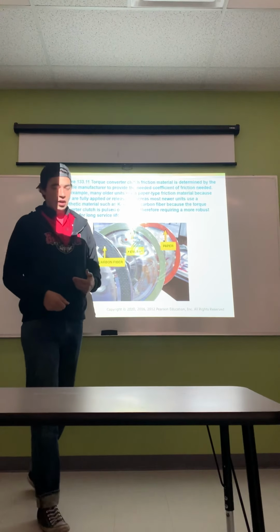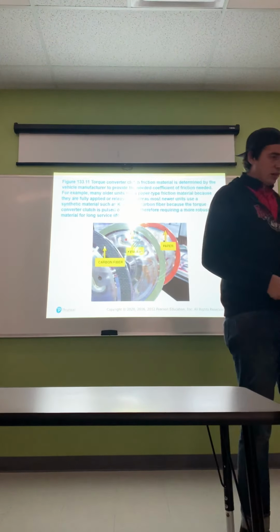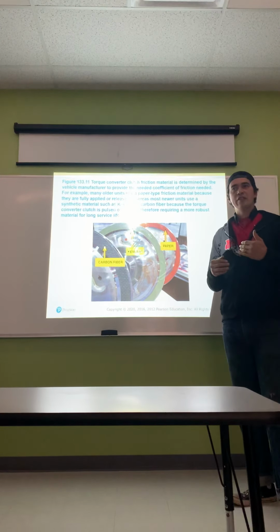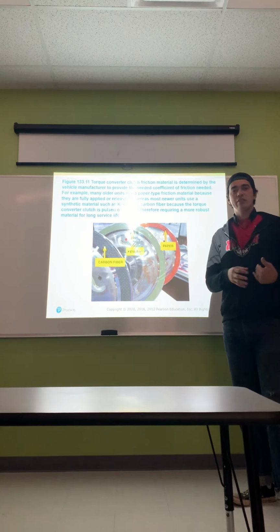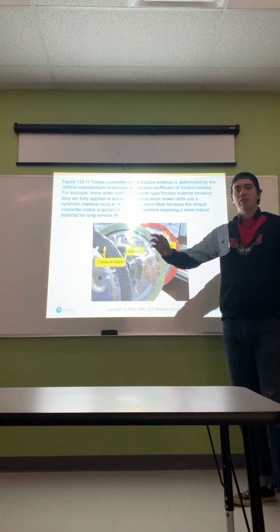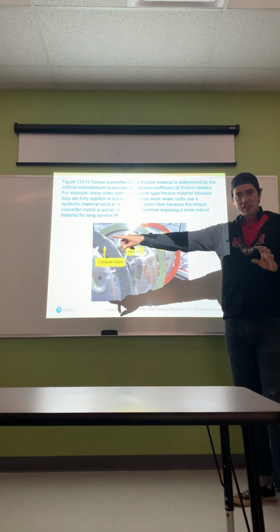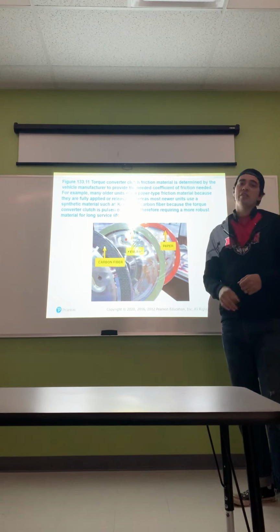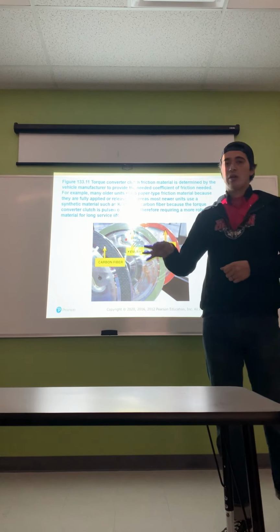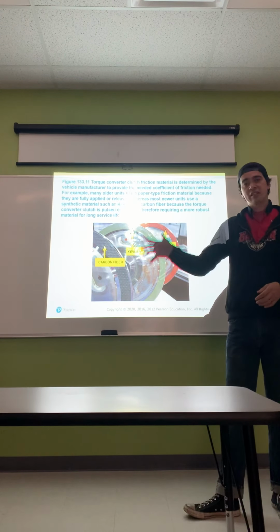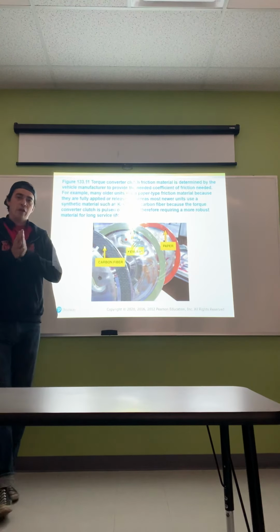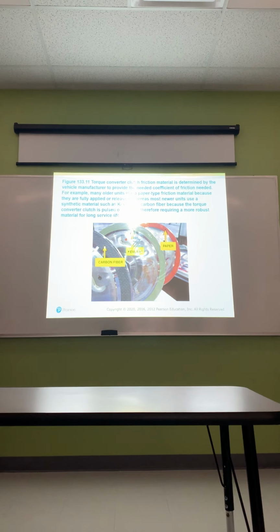gear. When we talk about the types of automatic and manual transmissions, you're going to see we have a different number set of gears. For manual transmissions, direct drive is usually fourth gear. That's the 1-to-1 ratio going from the engine through the transmission out the drive shaft. When we have an automatic transmission, third gear is usually our direct drive. So fourth gear is going to be overdrive for an automatic, and fifth gear or sixth gear is going to be overdrive for a manual transmission. So just remember, fourth gear for manual, third gear for automatic for our direct drive 1-to-1 ratio.